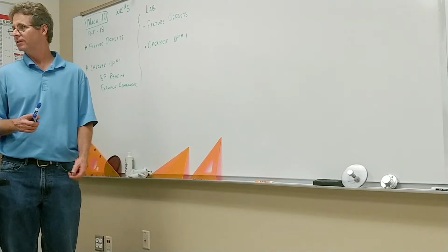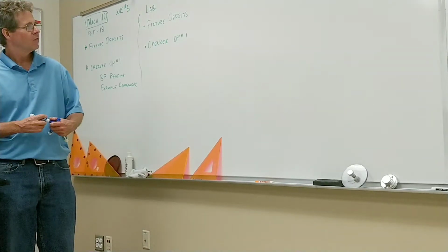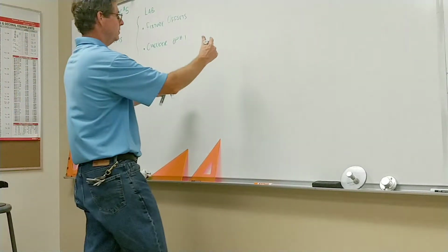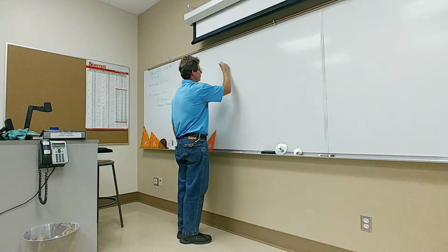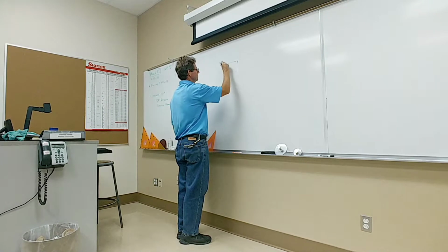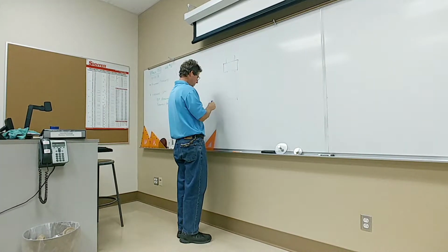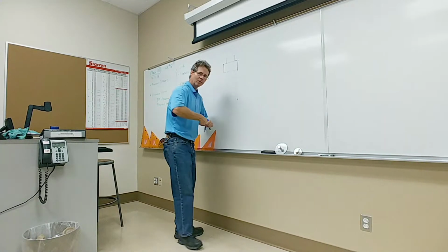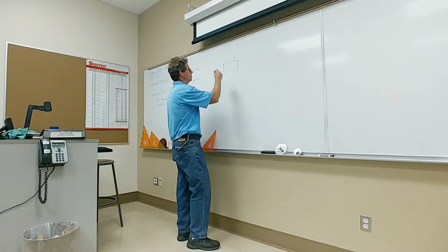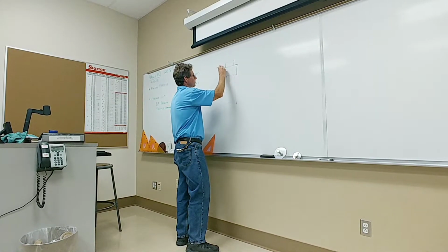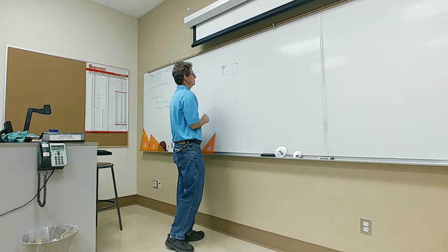part is. Okay, because, for example, let's say this whole whiteboard was the travel of my machine. Okay, I can put my part on the table, put it in a vise or some sort of fixture. I've got to tell the machine basically where the XY0 position is on my part. So commonly you put it on the upper left corner. Okay.